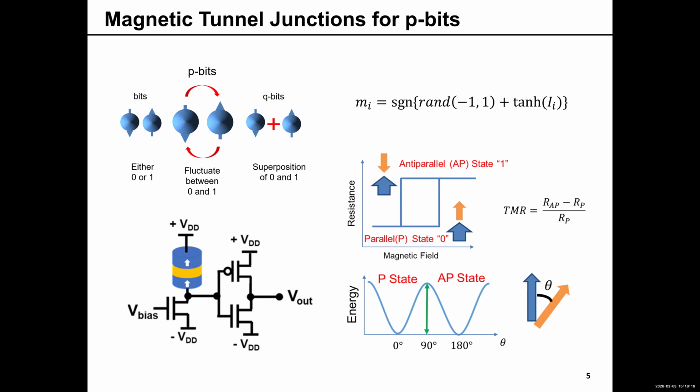And conventionally, if we want to use this magnetic tunnel junction for memory, we would design this energy barrier to be large so that the thermal energy from the environment is not likely to switch the device. However, in the context of this talk, I will be focusing on situations where this energy barrier is intentionally small, either statically small or where we lower it by applying a voltage so that the device exhibits stochastic behavior and generates random bits for our computing purposes.